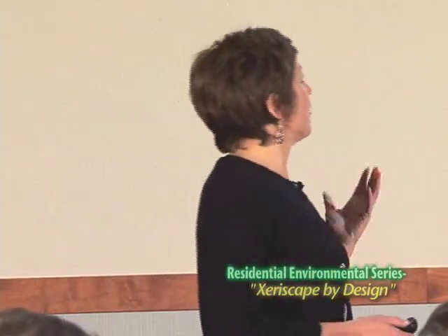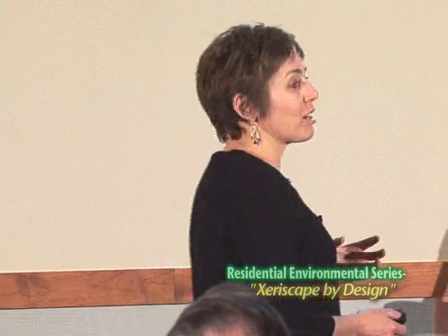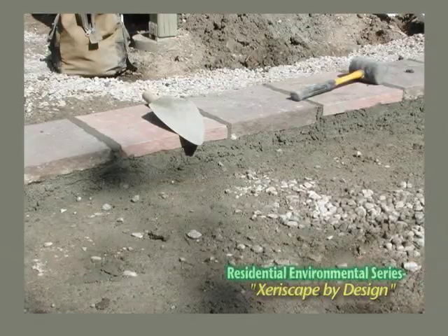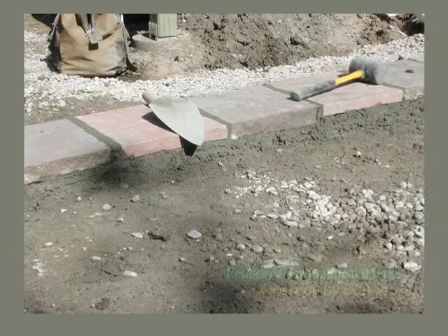So if you want a little bit more formal of an approach to a patio, but you aren't quite going to go to the most formal extreme, the construction technique that comes from the paver industry, and I'm going to talk about pavers next, is a road-base application. So what you see, ignore that stone on the side of the slide, that's mortar set on concrete, but in the front of the slide, in front of the mallet, is class 6 road base, compacted, and then there'll be a sand setting bed, and then the stone will go on top of it.